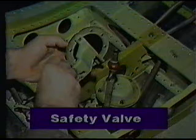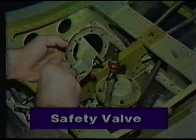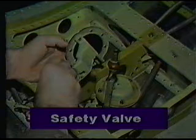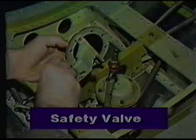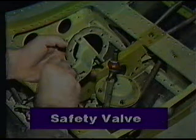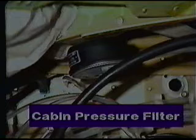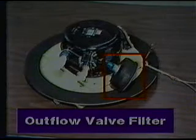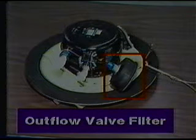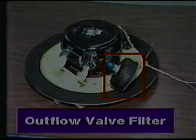It is not part of, nor has anything to do with, the door seal system. It senses the slightest amount of pressurization inside the aircraft and locks the door mechanism to prevent opening while pressurized. Filters used in the pressurization system include a cabin pressure filter that connects to the controller, an outflow valve filter that is located on the outflow valve itself, and a filter installed in the pressurization controller itself.